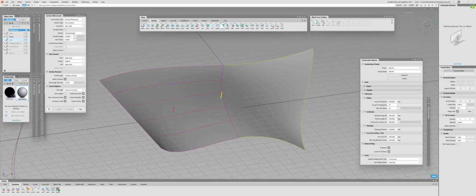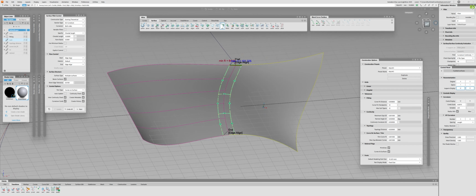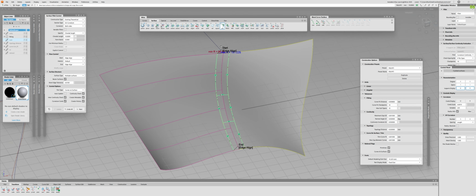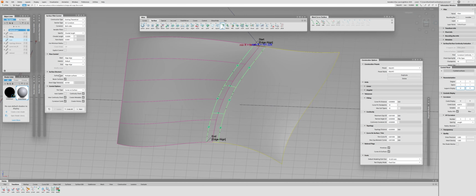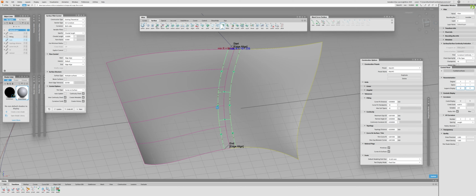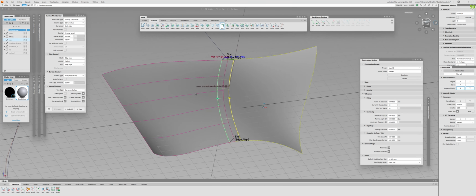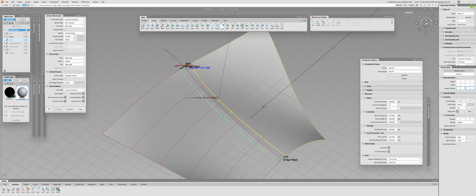So let me just click on this and build the fillet. Now I'm using existing theoretical, so we didn't really bend or do something. And as you can see, it creates three surfaces for me. Now that's because I am in the Bezier. If I uncheck the Bezier, it will create this amount of spans.